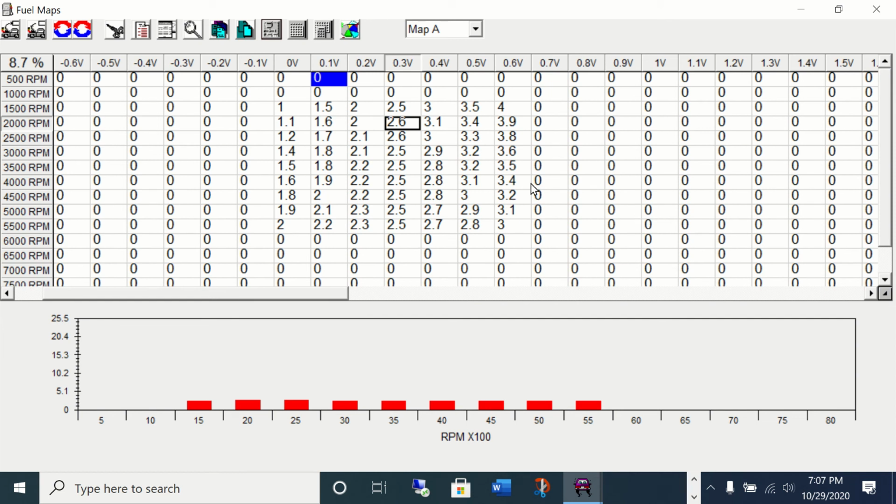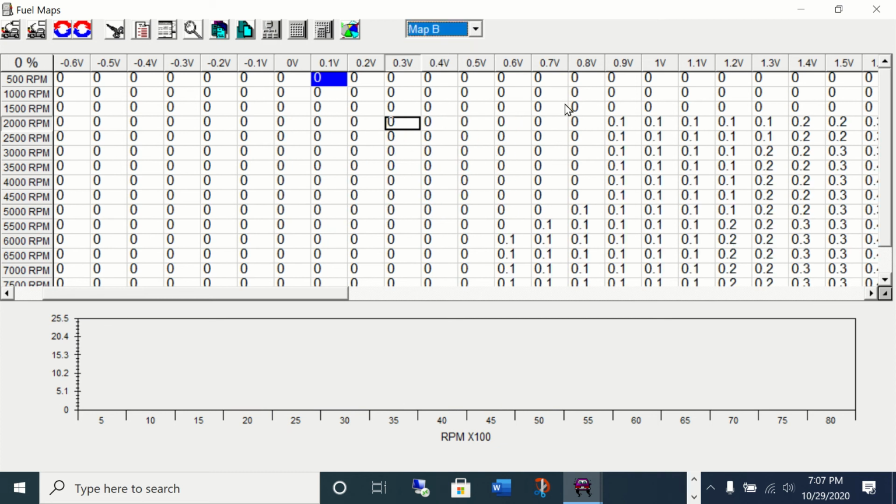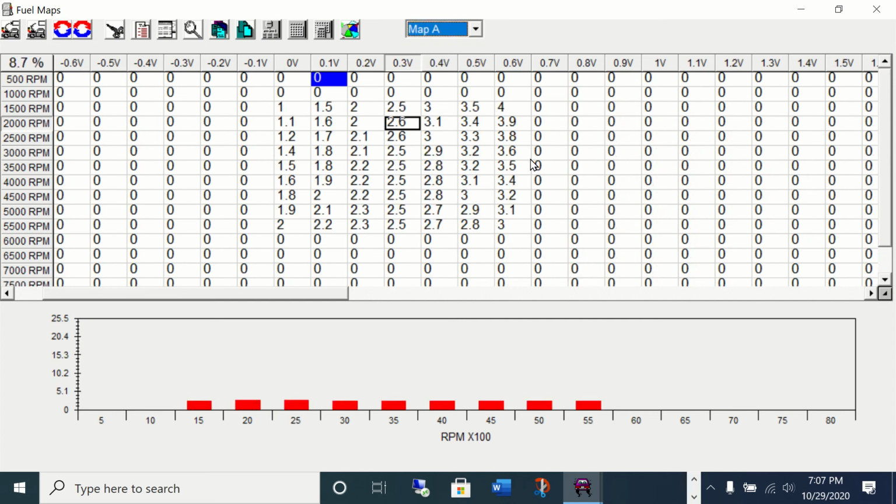So one other thing I'll mention is on the AIC family, AIC1, A4H, and G4H have 2 injector connectors that are driven off map table A and 2 driven off map table B. So if you have map tables A and B different, then the 2 sets of injectors will have different numbers.